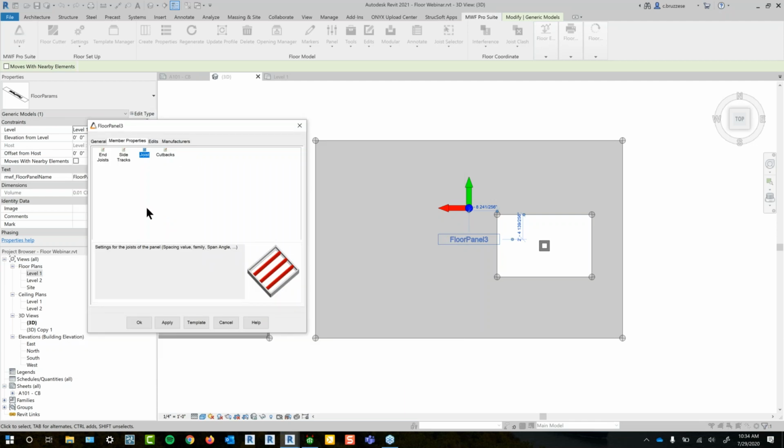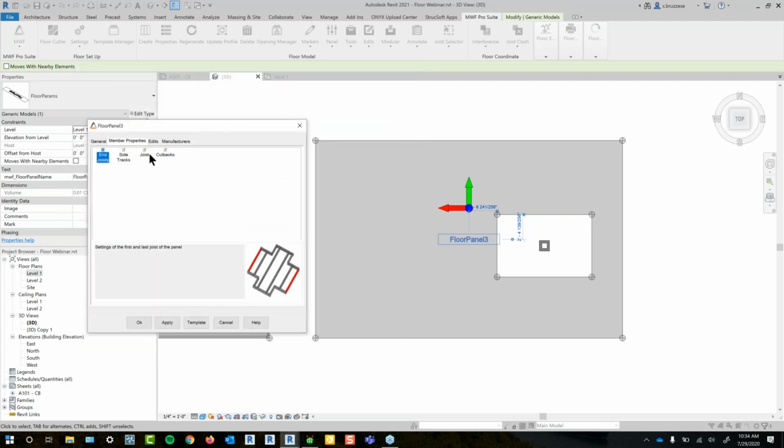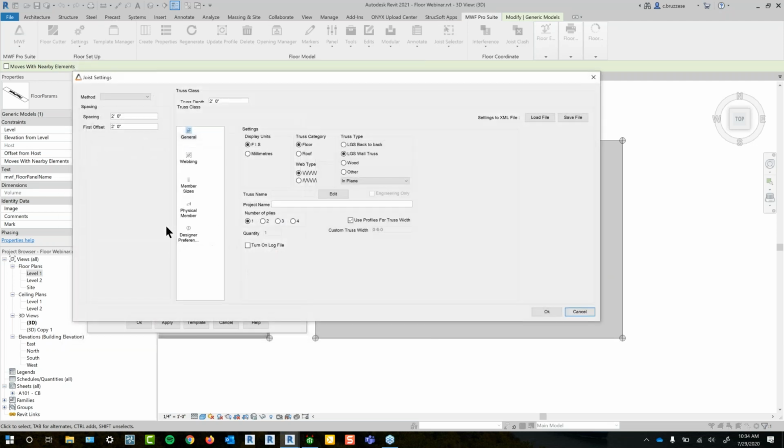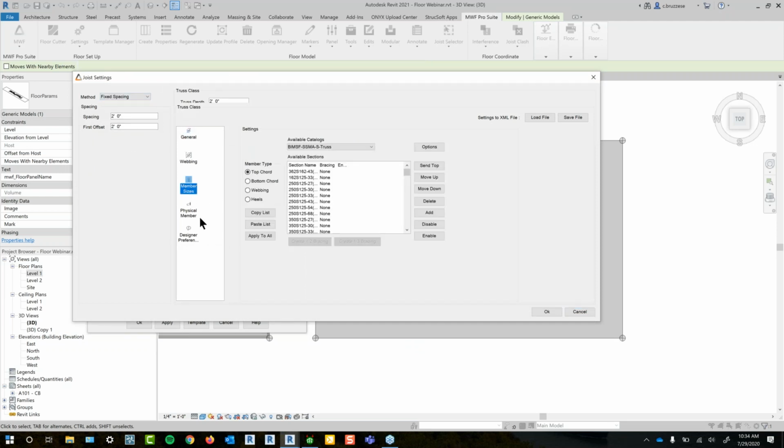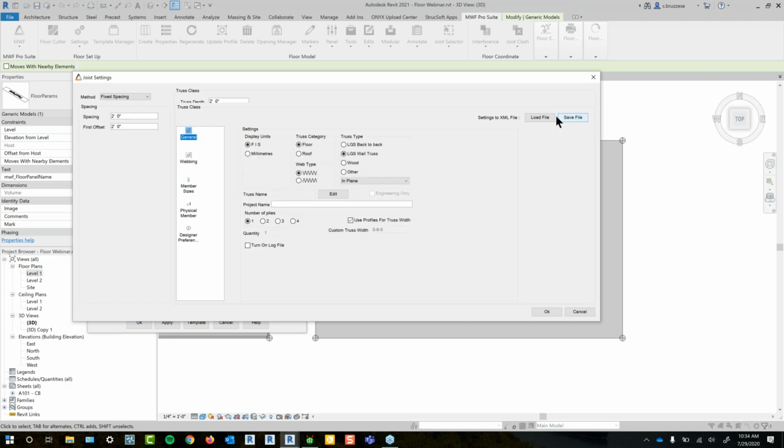And you do have to do basically the same set of settings for the joists or just kind of your trusses. And then in the end joists, which are just going to be, of course, your end trusses, they can have the exact same settings. So a little shortcut, instead of refilling the same presets 2 times, I'll go in the joists, I'll set up my member sizing, my webbing, basically get all this set up.